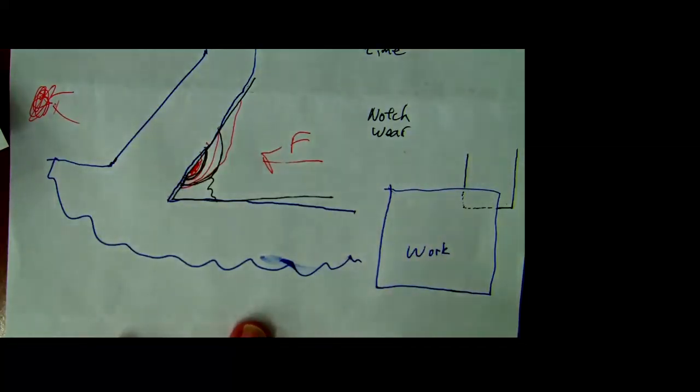And look at that workpiece. Where is the material going to most likely have contaminants, inclusions? Where is that material on that workpiece going to be the hardest because it cooled the fastest? The outside surface. So what will happen is, if I'm cutting like that, I might get a notch over there in the cutting tool.